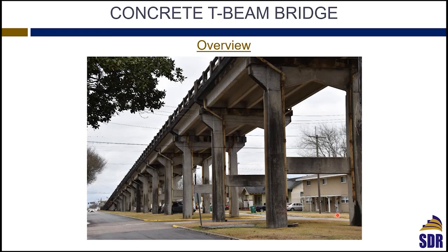However, in reality, the connection between the beam and the column is a stiff connection. This is an area. So we cannot assume that this beam is simply supported and will bend as if it's sitting on a hinge. There will be some negative moment developed at the connection, and even the column will experience some of this negative moment. That's why the beam-column connection is one of the crucial areas that we have to design for when we are doing concrete structures. By nature, concrete structures, especially cast-in-place reinforced concrete structures, have a lot of redundancy in the system.